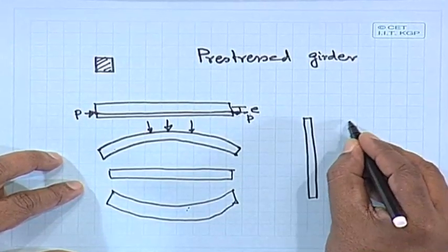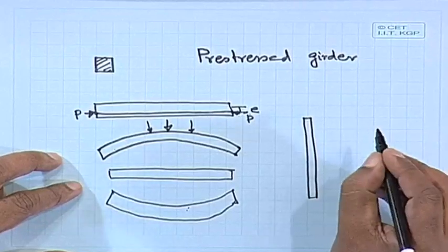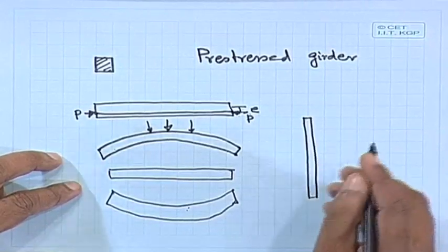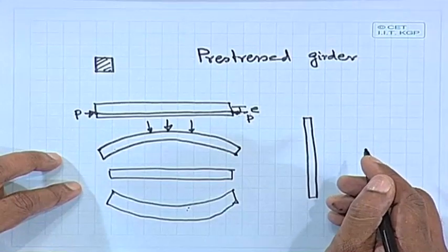But anyway, we are going a little away. Just to conclude, this is called a pre-stressed girder, and we can go 20 meter, 25 meter, 40 meter, which we shall not be able to do by reinforced concrete. Reinforced concrete beams, we cannot go 5 meter, 6 meter, 7 meter, maybe we can go to 10 meter, but your depth will be enormous. The depth you have to provide, because Mu = 0.138 fck b d squared. So from there you can find out the corresponding depth. If we have more span with the same load, your depth will be more.